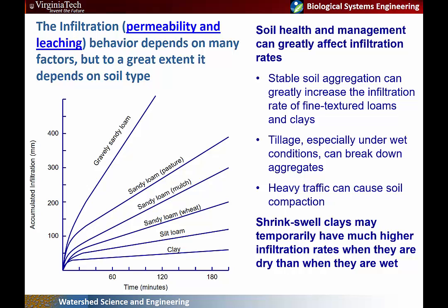These shrink-swell clays, which we really don't have too much of in this area of the Mid-Atlantic, but we do have some in other areas, temporarily have much higher infiltration rates when they're dry than when they're wet. When they're dry, they split open and can infiltrate huge quantities of moisture. When they wet up, those soil fractures close and they behave much more like a traditional clay.